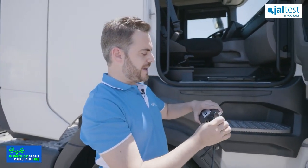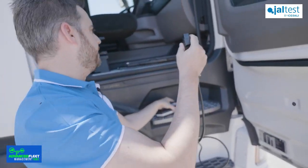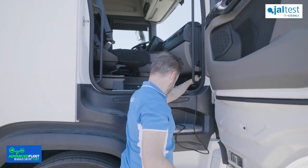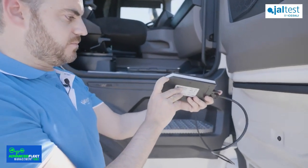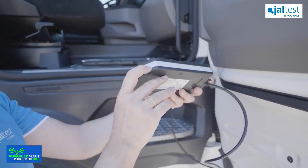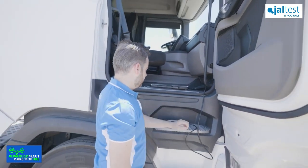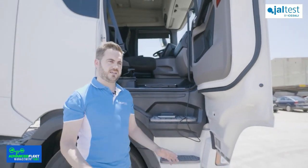We plug the OBD2 connector into the Jaltest Link and connect to the diagnostic port. Then remember to make sure that the blue LED is on in order to make sure that we have enough power supply. Finally, we just need to make sure that we have the key on.